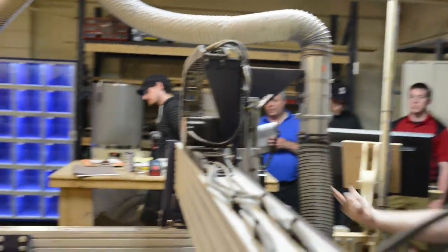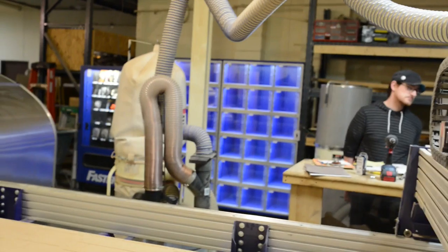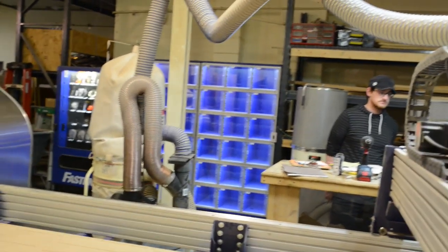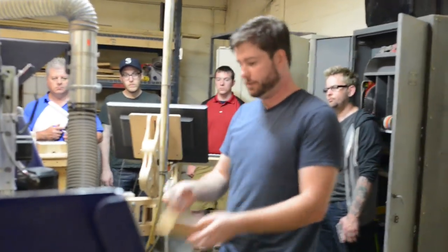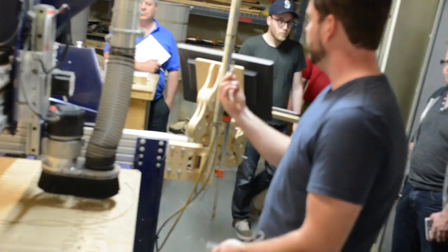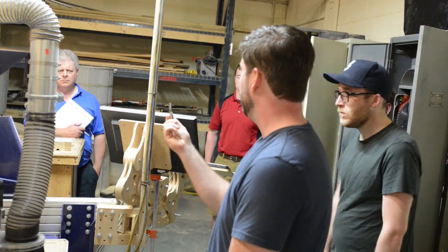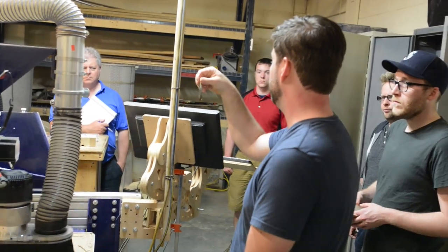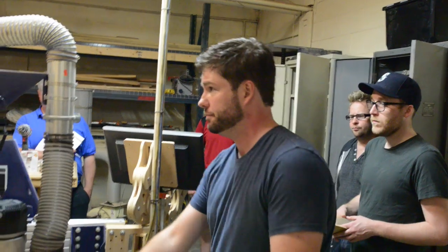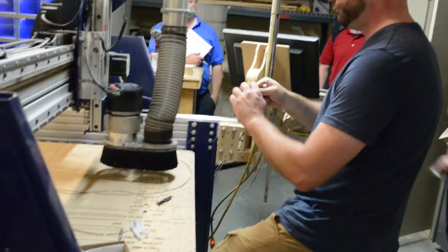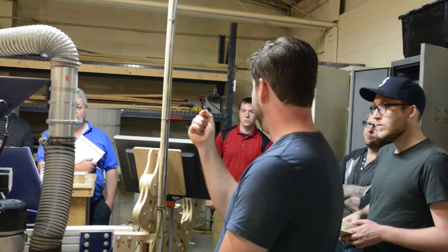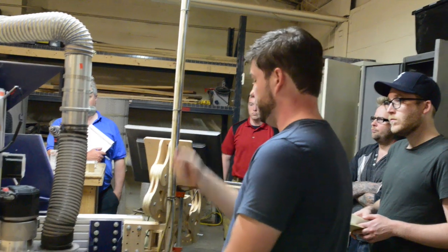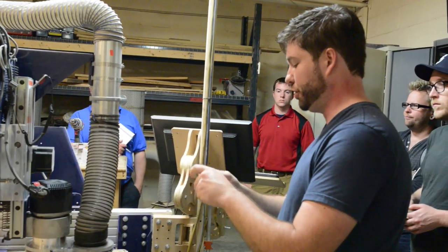So it comes all the way down here, and it's got this dust strip. We got to put the bit on first, our router bit, and our router bits, I'm going to show these to you real quick. Router bits come in all kinds of different shapes and sizes. We got the big, the solid carbide. This is an upcut bit, 2 spiral, 1/2 inch thick. We have kind of the same exact thing, just really small, solid carbide. I think this is an 1/8 of an inch upcut bit. Just all depends on what you're doing.